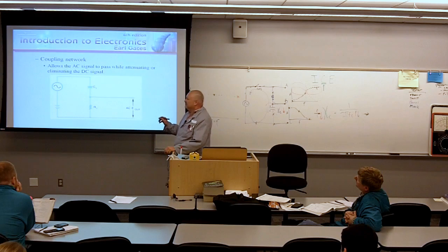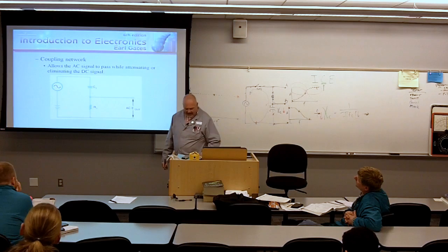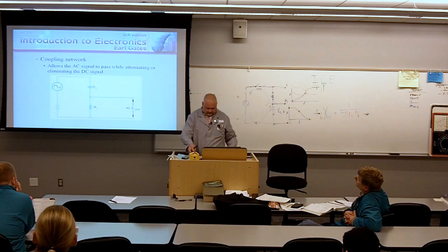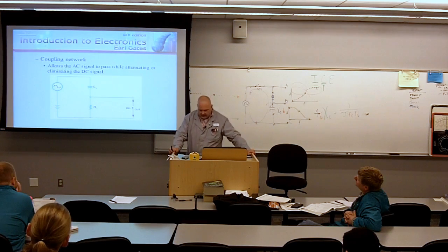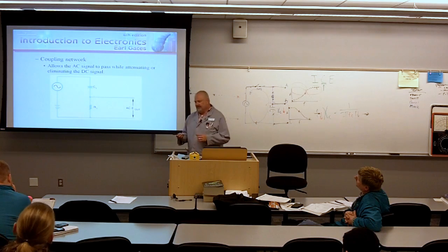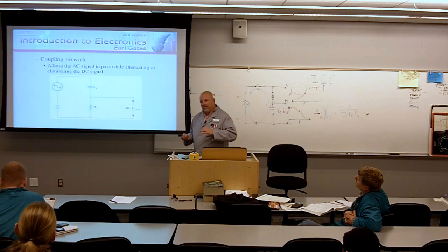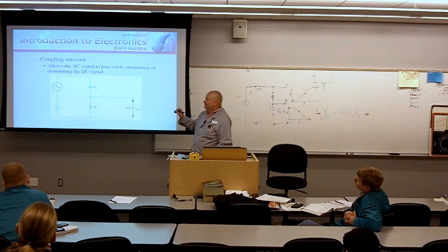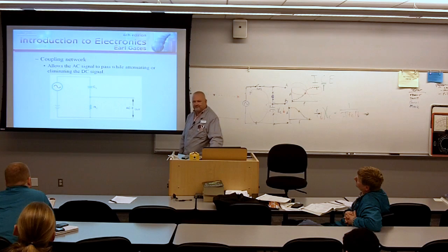What do we have here? It's a series DC-AC series RC circuit, same exact circuit. How are we connected here in the circuit? We're taking the output across the parallel resistor. Because what's happening? The DC here is getting what? Blocked by this capacitor. What's the AC doing? Flowing through the capacitor, and as it flows through, does AC generate a voltage drop as it flows through a resistor?